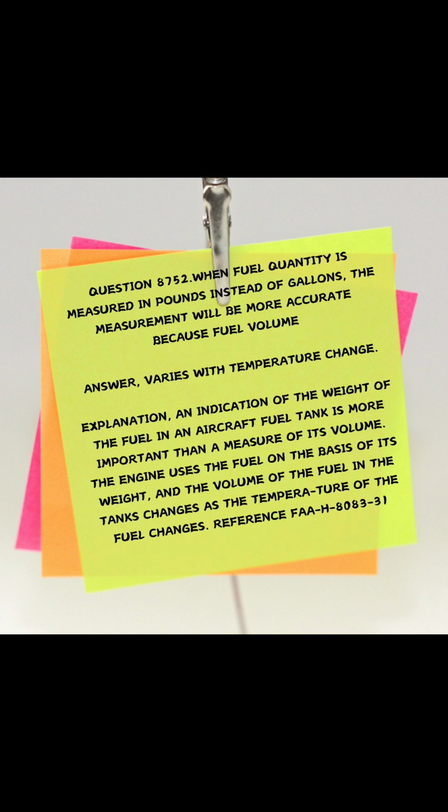8083-31. Question 8752. When fuel quantity is measured in pounds instead of gallons, the measurement will be more accurate because fuel volume. Answer: varies with temperature change. Explanation: an indication of the weight of the fuel in an aircraft fuel tank is more important than a measure of its volume. The engine uses the fuel on the basis of its weight, and the volume of the fuel in the tanks changes as the temperature of the fuel changes. Reference: FAA H